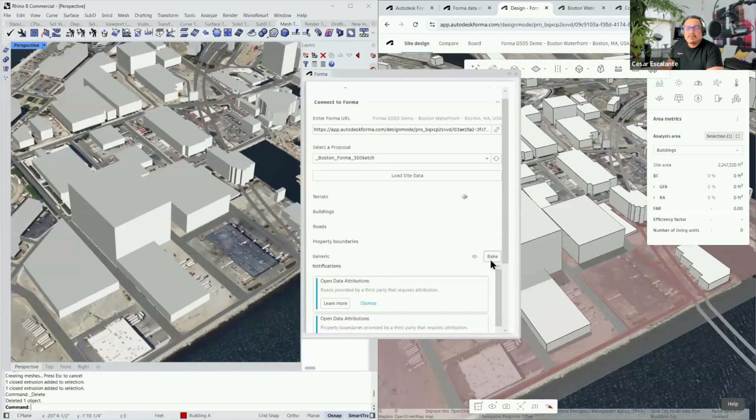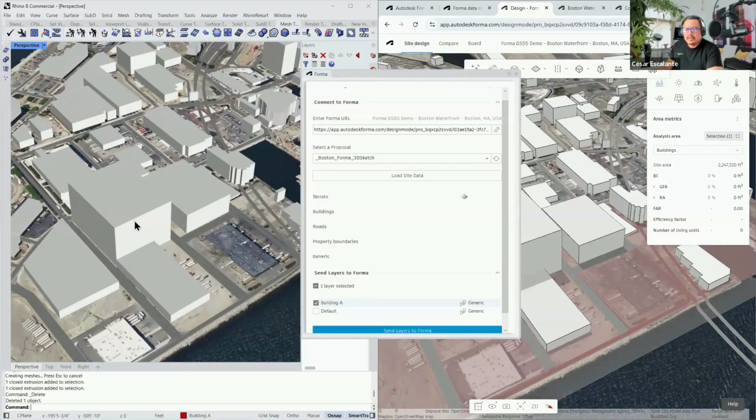Unfortunately, right now, you don't have a capability to convert it into solid, but inside Rhino, you can convert a mesh into NURBS. And if you need to troubleshoot, there are different ways to rebuild boundaries when they don't come across neatly. But that is how you go when you start from Forma and then you continue design in Rhino.